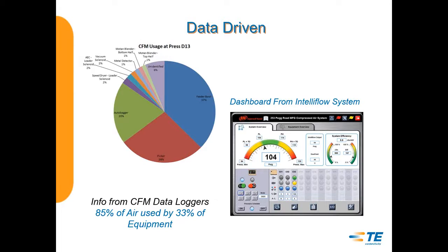So not only from an air leak standpoint, where we're reducing our usage, we tried to improve the efficiency of how we actually compress the air too. So we installed a 3,000 gallon tank. That gives us time enough to drop a compressor out, bring another one on without seeing any degradation in our air pressure across our main manifold. So that system gave us the visibility to see what we were doing from an air leak standpoint and what kind of impact.